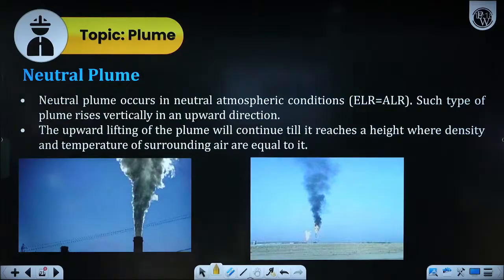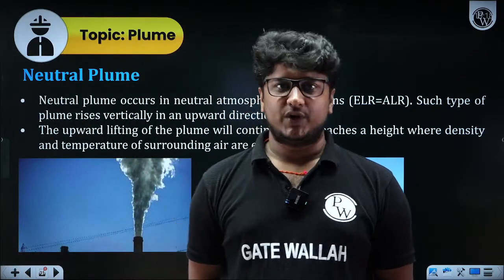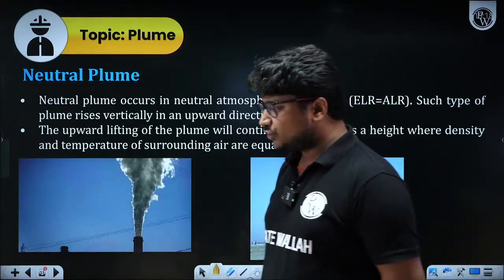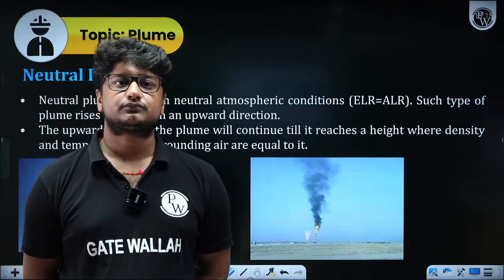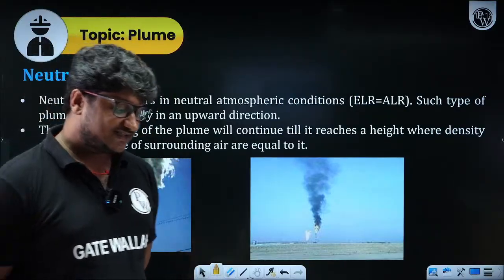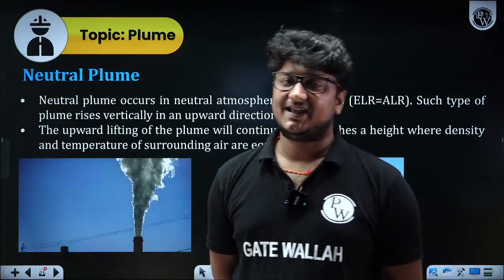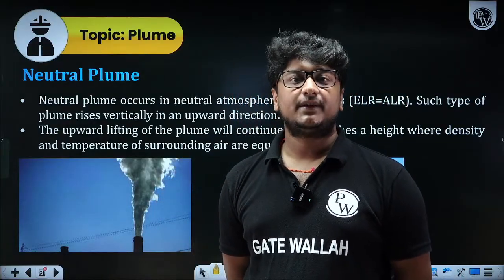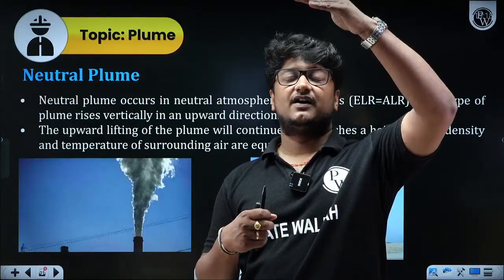So this is the last plume behavior case. I have discussed how many? The first one was looping, second coning. Looping is for super adiabatic condition, coning is for sub-adiabatic condition, then fanning is for inversion layer.